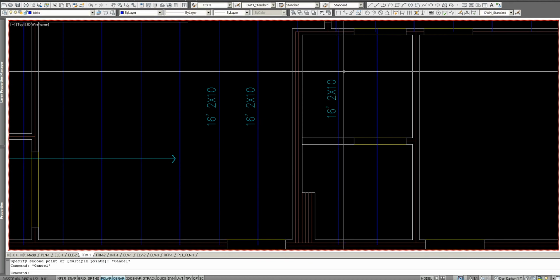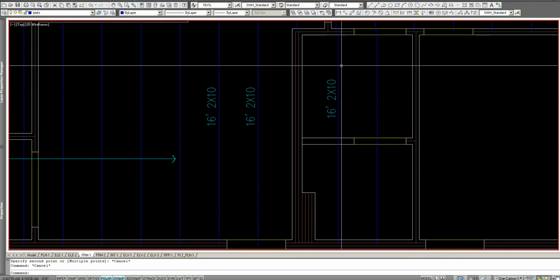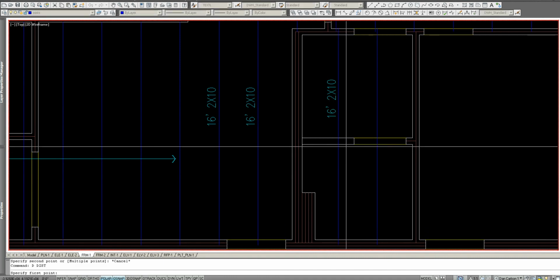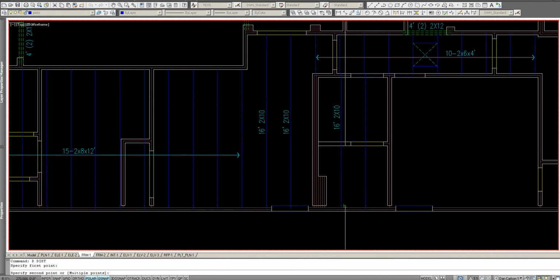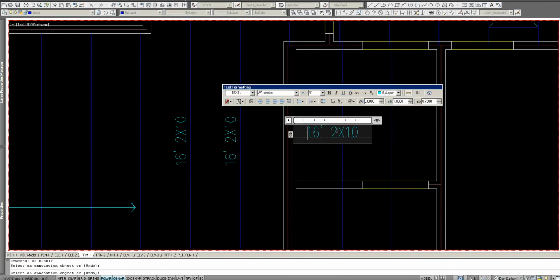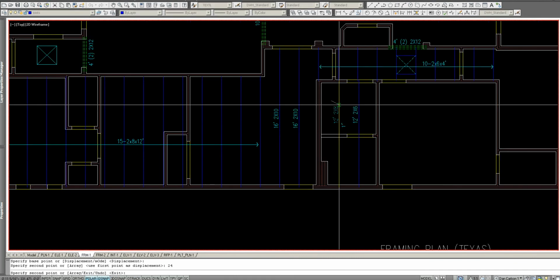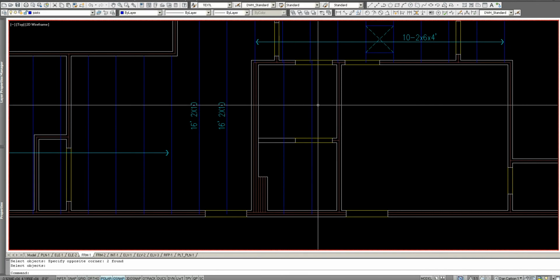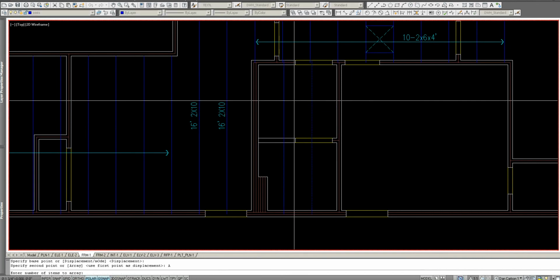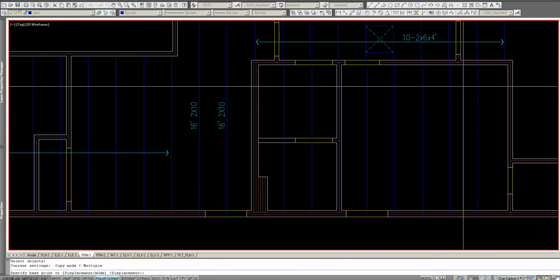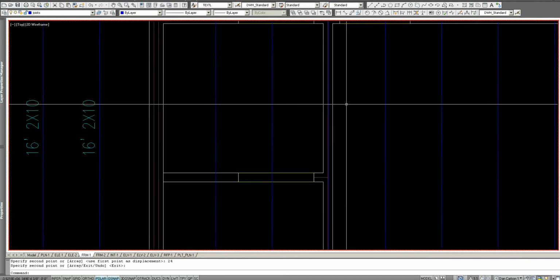So these can be 2 by 6s, but they're going to be the full length. We're not going to put a 2 by 6 here and then a separate 2 by 6 here. We'll just do one 2 by 6. So that'll be a 12 foot 2 by 6. There we go. Well, we're going to have a whole row of these, so I apologize. Let's just array this 6 times. We're going to require one. Yeah, why not? We can erase this one, though.